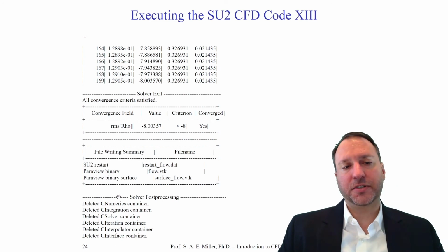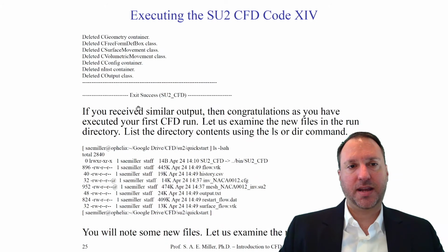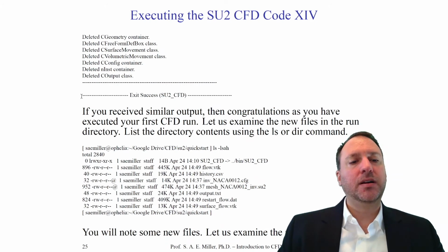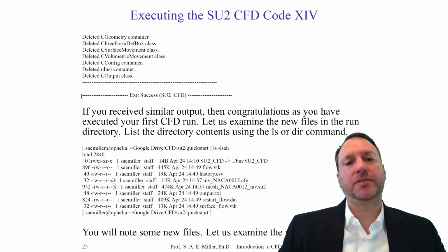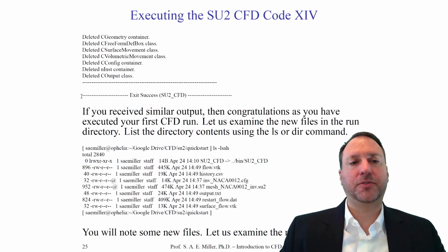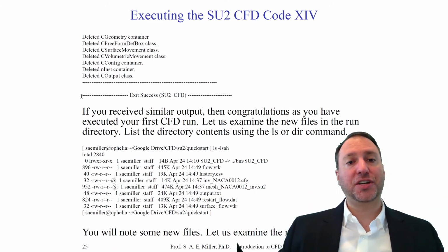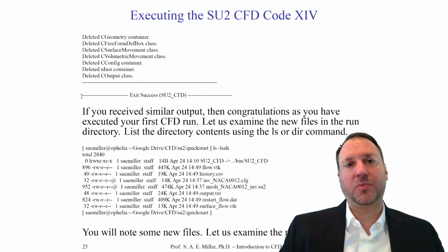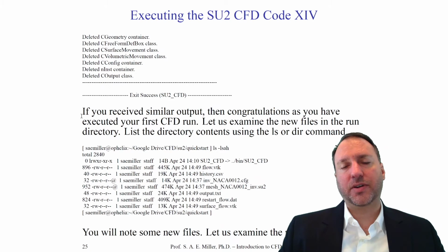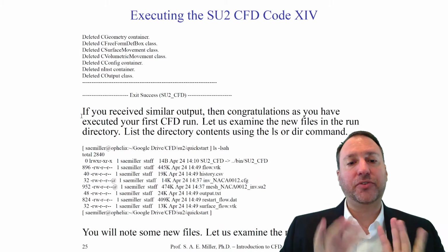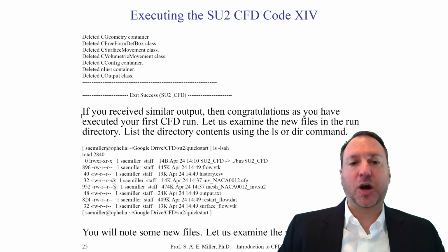Nonetheless, the solver does some cleanup. It's deleting extra little containers of files and things. And of course, it exits successfully. When you see this particular command, your solver is done running, and your command prompt returns. If you return and see a similar output, then congratulations, you've run your first CFD run using the SU2 solver, and you've executed the quick start tutorial. So let's examine the new files in the directory. The solver is done. Let's look at the output files.